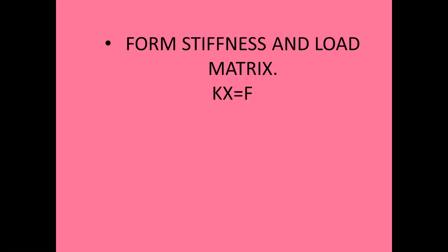Therefore, when I say that the X matrix is of size 1 column and 10 rows, I am considering all 10 nodal displacements as unknowns. I am not taking the value of displacement at node 1 and node 10 as the known values.